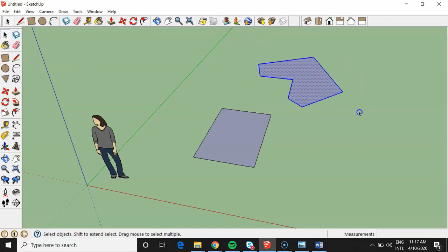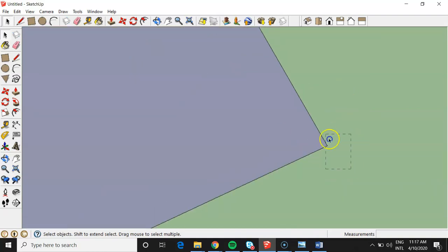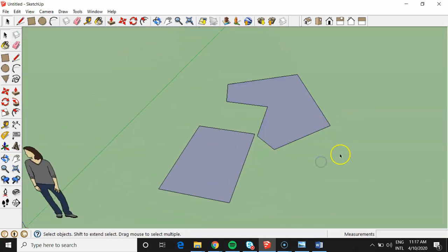So let me talk about the selecting as well here. So when I drag a window from the left, like CAD, everything that's within that window will be captured. So you can see I'm touching the rectangular box, but nothing is fully in it. So I'm just getting this shape up here, and I could come from the bottom right, also like CAD. And when I come from this direction, it's very handy and noteworthy that anything that touches the box gets selected. This is in CAD and in this program. When I want to select things, this is the most common way to grab things.